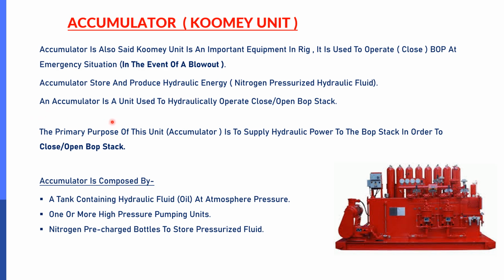An accumulator is a unit used to hydraulically operate, close and open the BOP stack. The primary purpose of this unit is to supply hydraulic power. The function and motive of the accumulator is to supply hydraulic power to the BOP stack in order to close and open the stack. This is the simple definition of the accumulator.